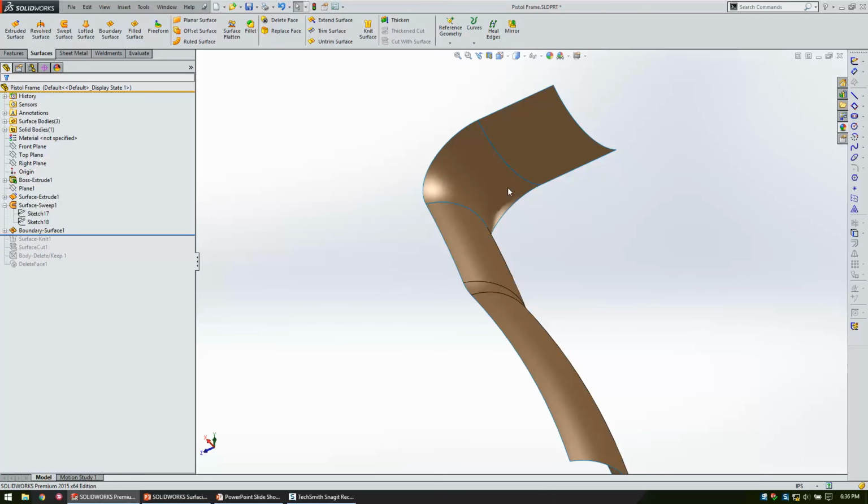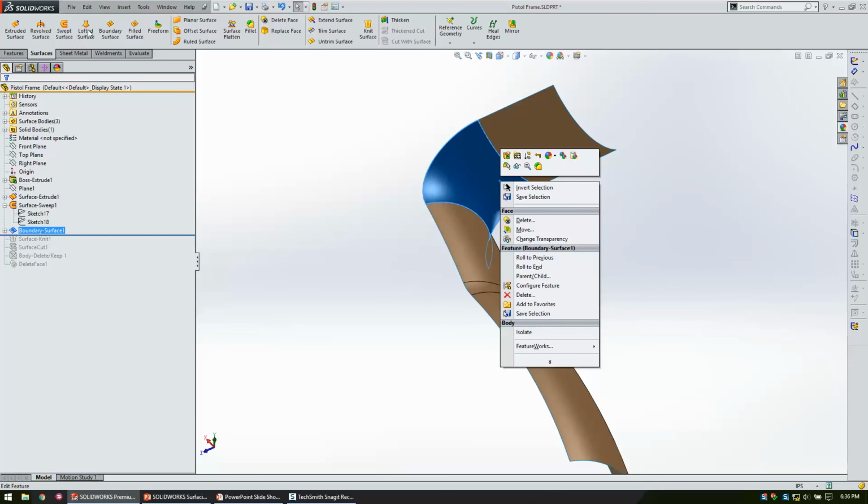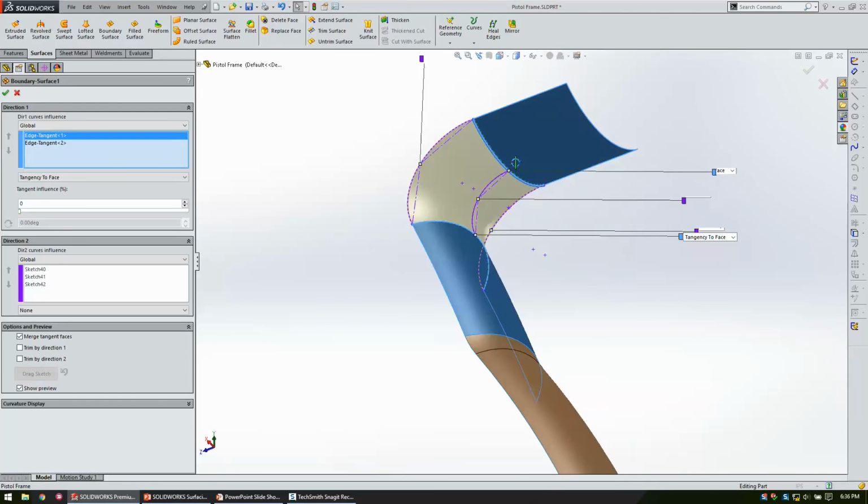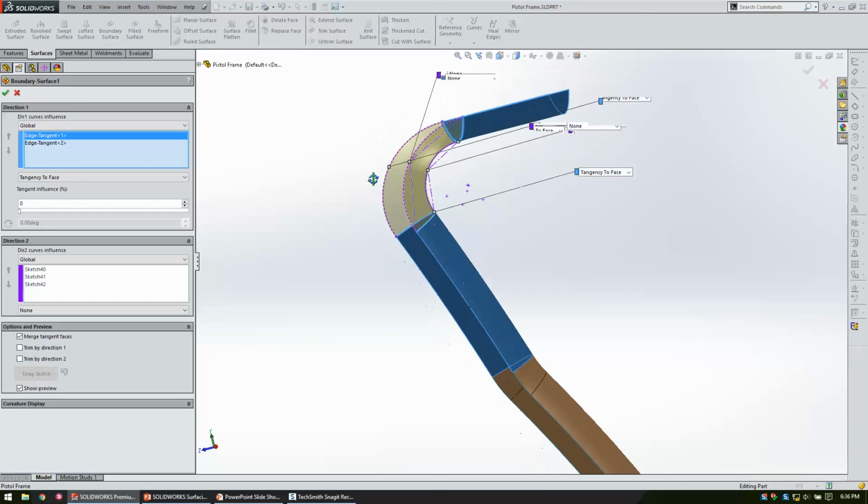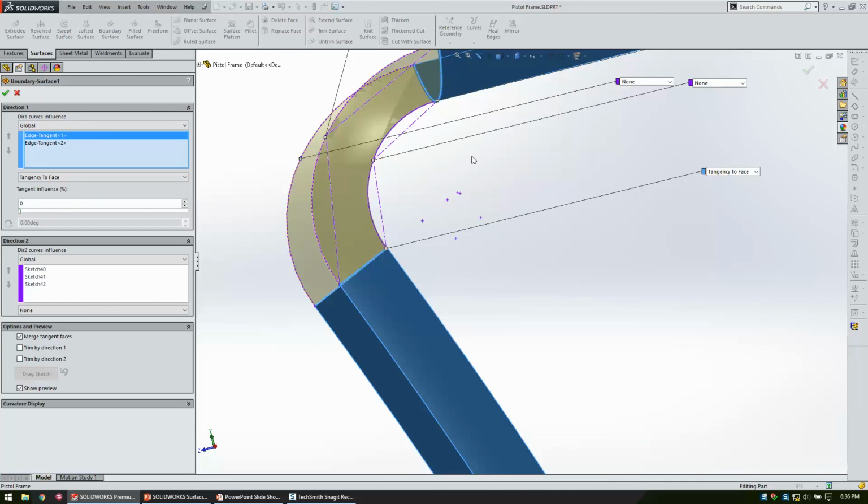The only thing that I want to loft over, which I used the boundary surface for here as the replacement of the loft, is this one face. If I had a sketch that came over here, I would only be lofting maybe a 1/4 inch, and on the other side I'm lofting like 1 inch. So you'd get a very weird loft on the other side, because the 1/4 inch and the edges are constraining that loft to try to keep it uniform and consistent. I mean, that's just how lofting works.